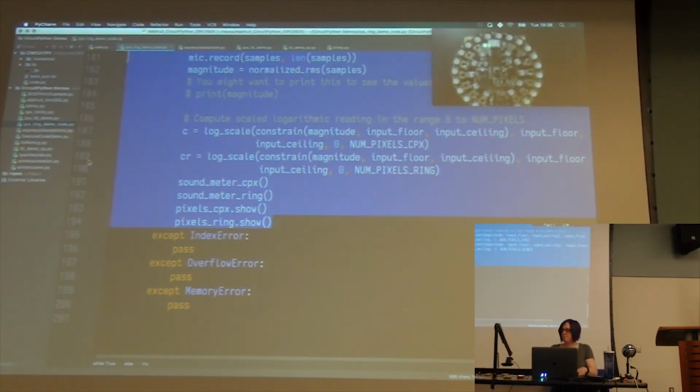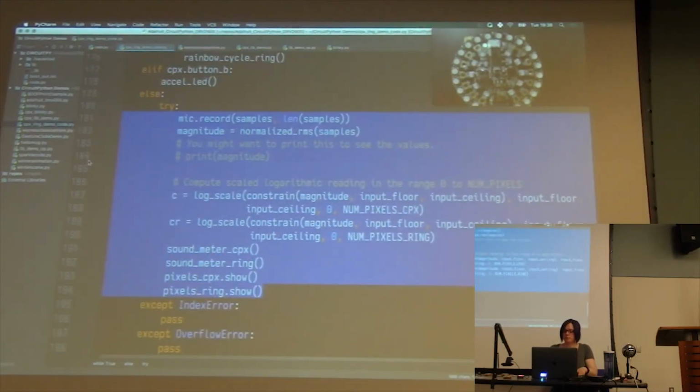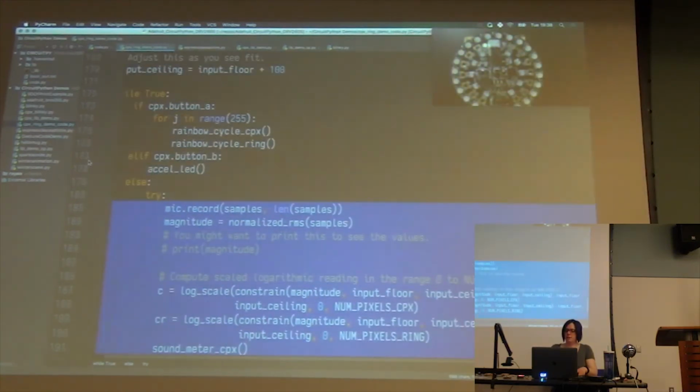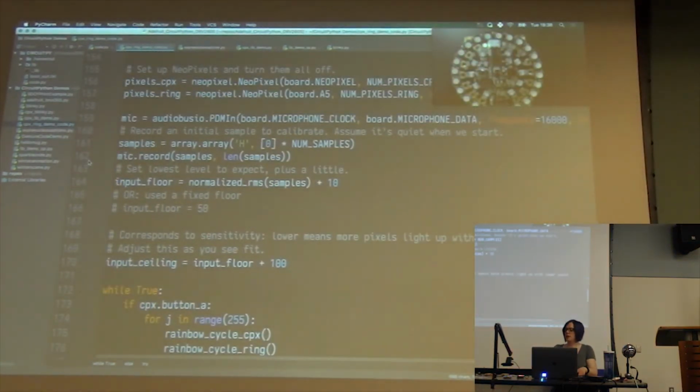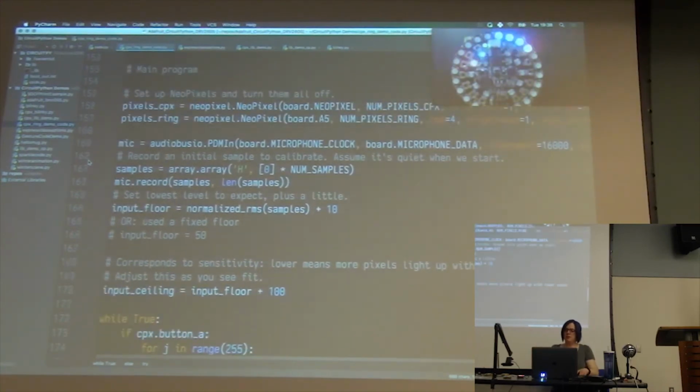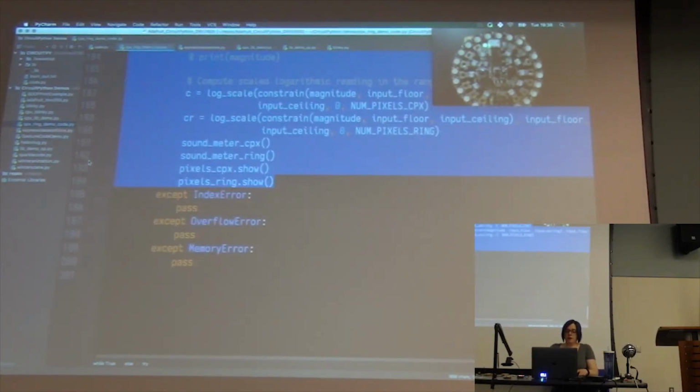Is that white level a byte, or is it just on or off? Say, which one? On the outside, on the W level? Yeah. Is it a full byte, like 0 to 255? Yes. So all of them on would be 255, 255, 255, 255. And so, yeah, that's how they ended up doing the RGBW. The white pixel actually looks bigger than the rest of them. It's significantly brighter, but even though they have strips that are all white, and it's actually 3 white LEDs, it's still exactly the same thing. It's all 0 to 255.